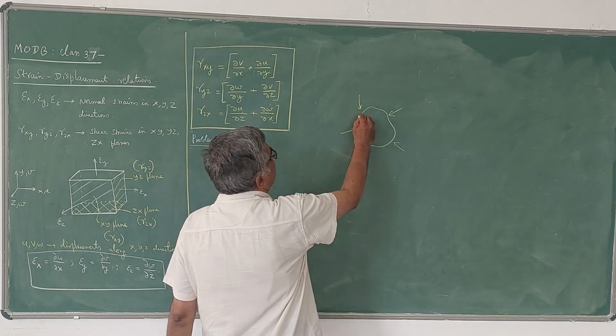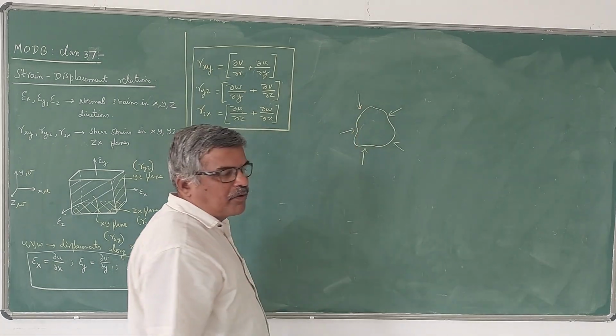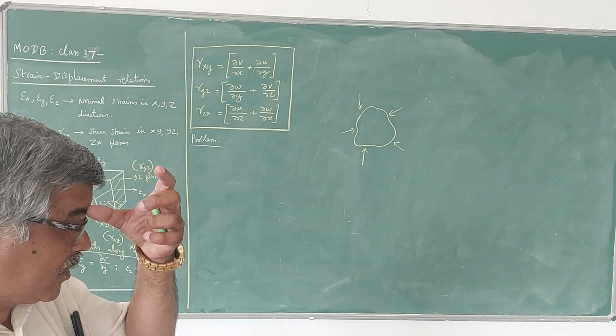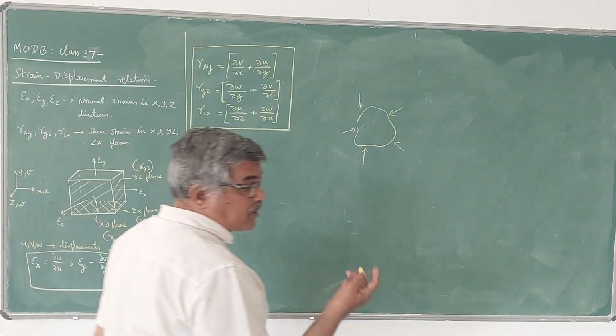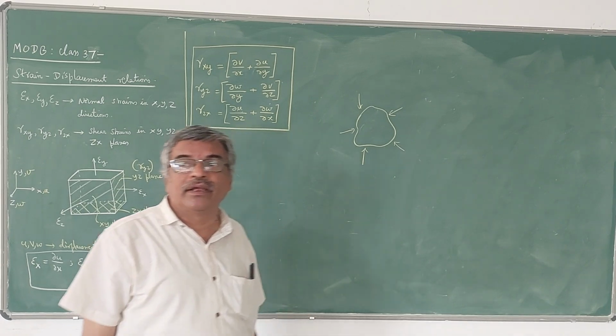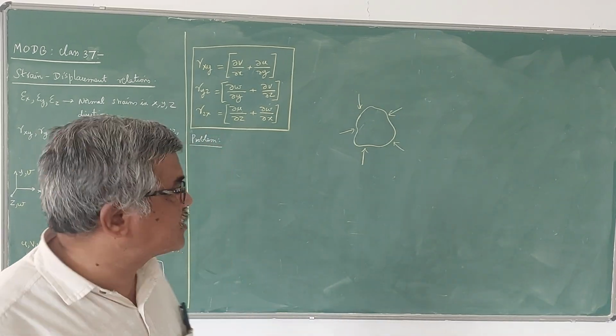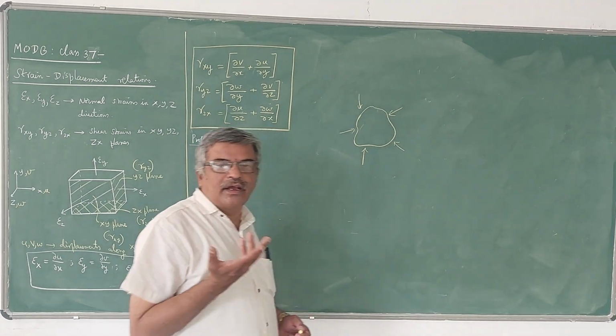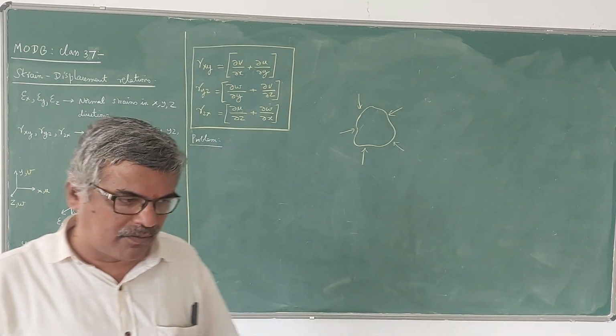Those stresses will be developed due to the strains induced within the body. Actually, strains can be measured, but stresses can only be calculated by knowing the stress strain relationships. So the strain is nothing but an idea about how much the body deforms.